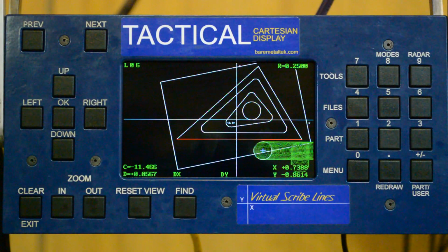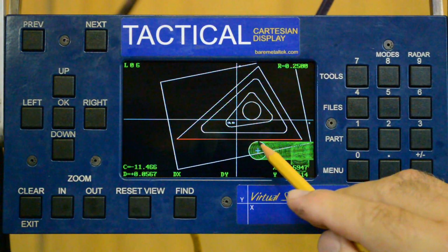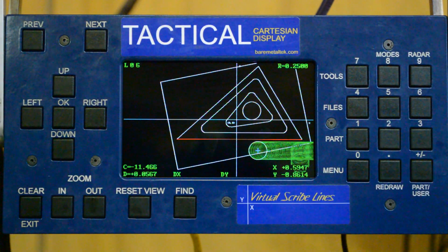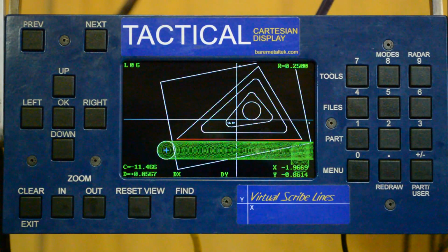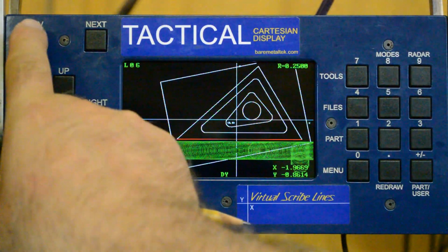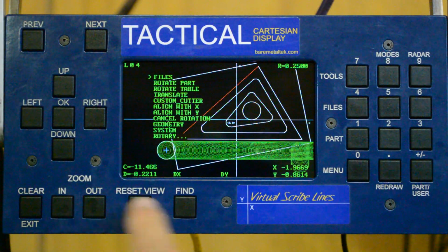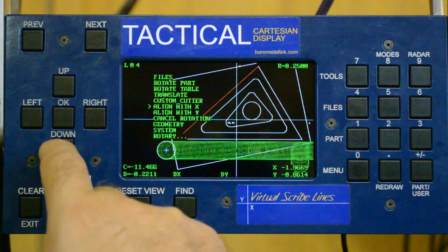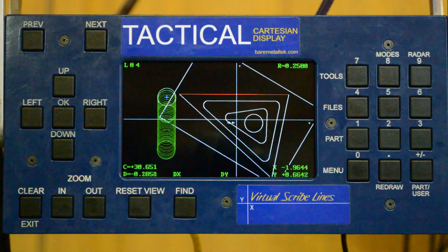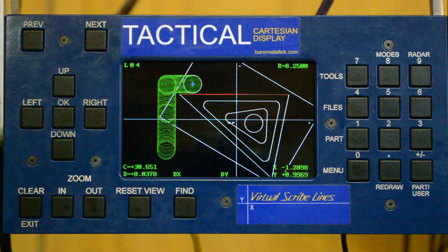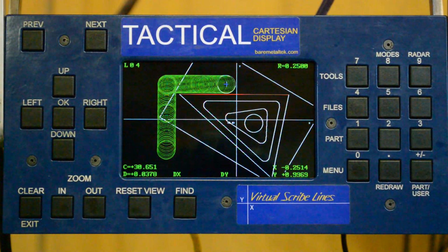And notice I'm leaving material. Look at the gap between the tool and the line. I'm staying away from it optically, and I'll make however many passes I need to get to the bottom. Then I'm going to go to, say, this line, and I'm going to make that parallel to the x-axis. Then I'm going to come down in Z, set my Z depth, and make a few passes in Z like this.